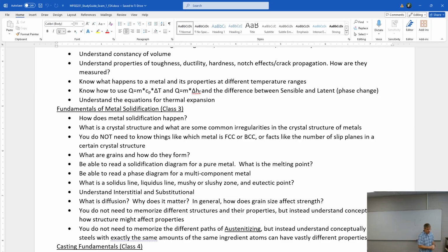And so then you need to do something to reduce that. But we also see it in other places, like we see it in the structure of a material when we talked about austenitization. If you cool the material really quickly, you get this super brittle, hard material. Some of the reason that it's brittle is because it contains these little collections of carbon that have very sharp ends on them, internal to the part. So when you load it, those ends of those little sections are very small radius notches, and so they will propagate a crack or a dislocation through the part, causing it to fail brittlely.